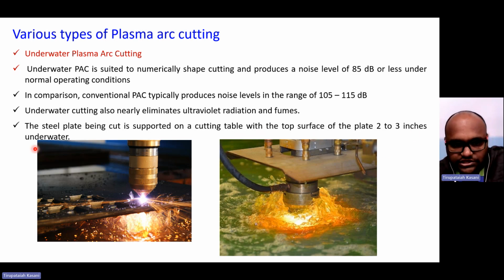Okay, 2 to 3 inches under water is the minimum, which results in controlling or eliminating the UV radiation and the fumes. That is an advantage with this plasma arc cutting. And this type of cutting is very much helpful in repairing shipbuilding equipment and submarine outer structure elements.